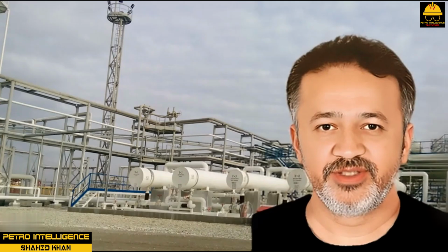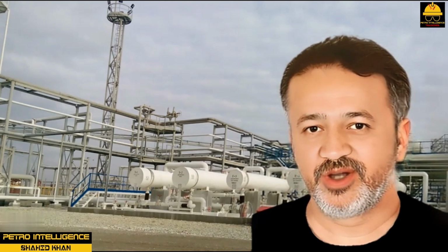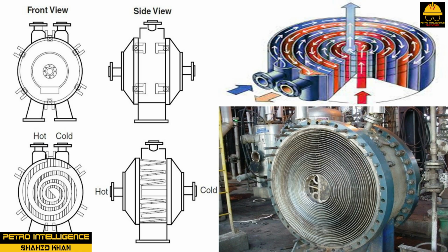Spiral heat exchangers. Spiral heat exchangers are characterized by a compact concentric design that generates high fluid turbulence in the process medium as shown in picture. This type of heat exchanger comes in two basic types: 1. Spiral flow on both sides, and 2. Spiral flow cross-flow. Type 1 spiral exchangers are used in liquid-liquid, condenser, and gas cooler service. Fluid flow into the exchanger is designed for full counterflow operation. The horizontal axial installation provides excellent self-cleaning of suspended solids.